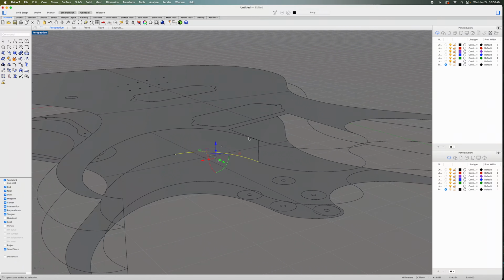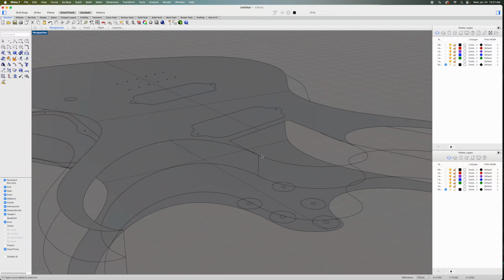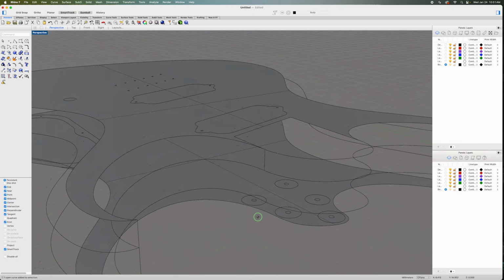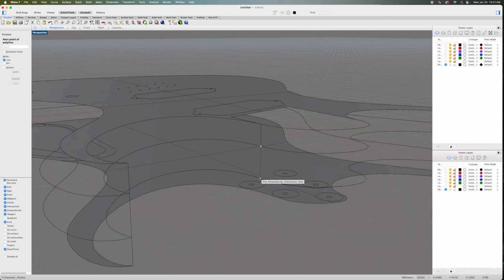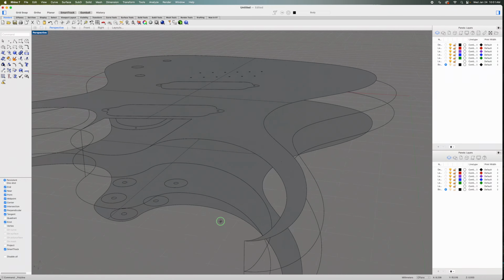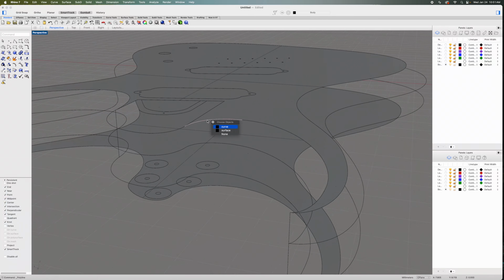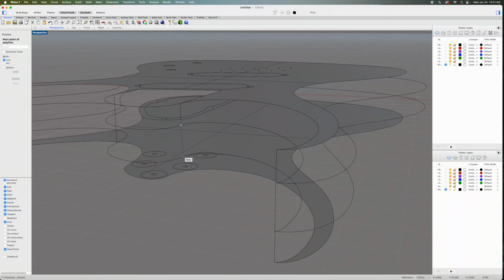And that's going to form the boundary for this shape that's going to be forming that bevel on the cutaway. Then I have to draw another polyline from this section down to this section here. And on this side, I need to do the same thing. So I'm going to select this curve just so it's easy to see. Go from that end down to this end. Then I will go from that end down to the end perpendicular intersection knot. Now I have those lines defined.